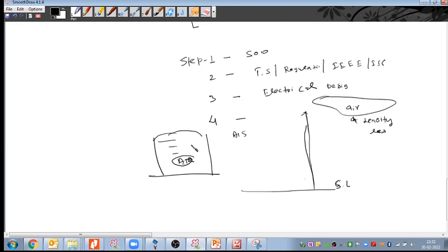So when we consider the equipment rating, since the air density is reduced, the insulating medium between this equipment and that equipment is less. So whatever the clearance is required, the flashover may go directly to this equipment also.